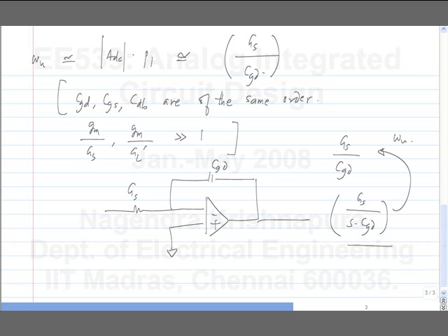We also know that this is more or less true if the op amp is non-ideal, meaning if it has finite gain and so on. If the op amp has finite gain, then the integrator itself has a finite DC gain. It does not have infinite DC gain. That's what happens. So, why does the ideal op-amp give you this transfer function?